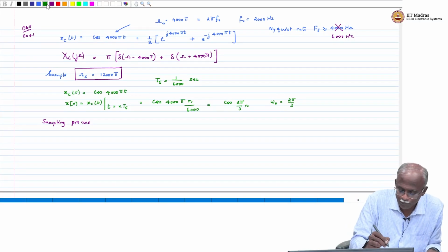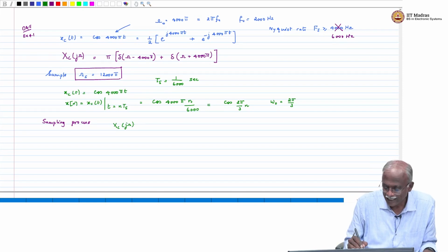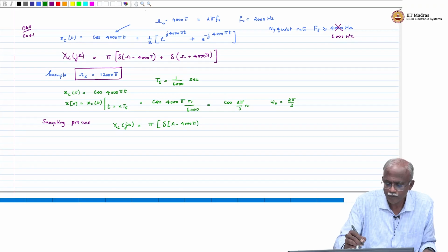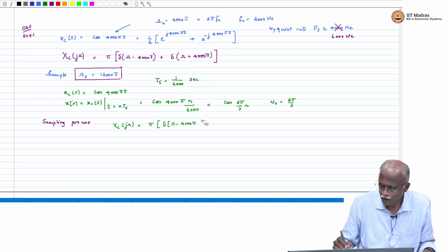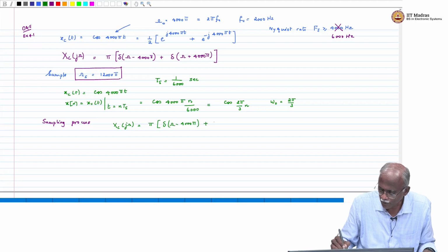So first step is you are going to say, okay, what is xc of j omega? That is the continuous time signal. The continuous time signal is pi times delta of omega minus 4,000 pi plus delta of omega plus 4,000 pi.